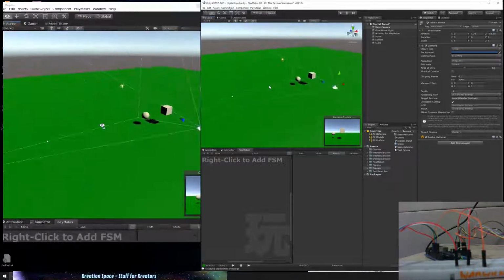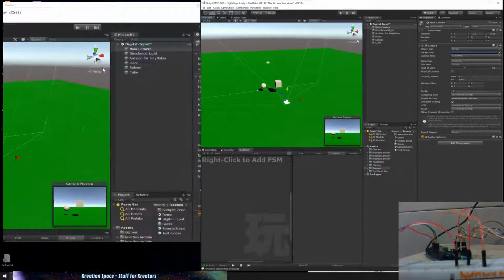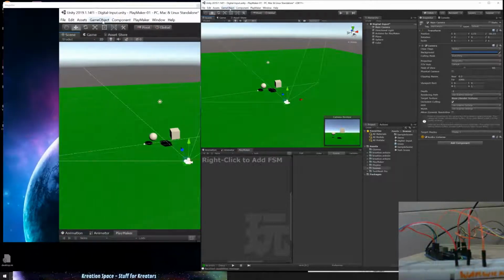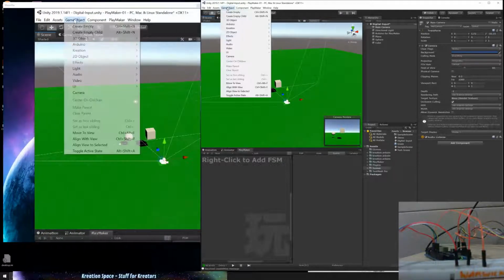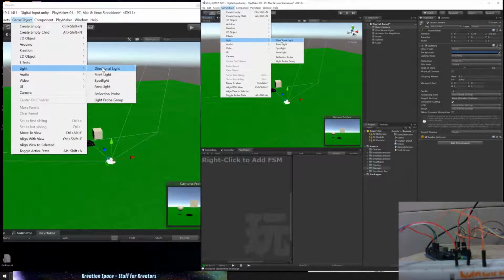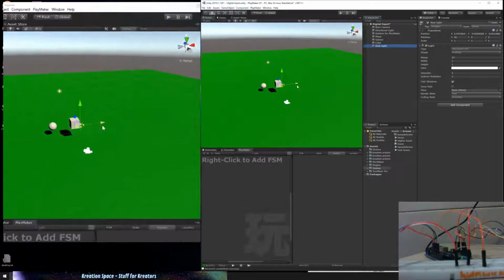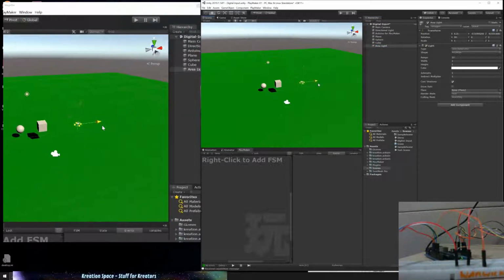Now, one thing that'll help, and it's always good to think about lighting in a 3D scene. So let's set up another light on the side to give kind of just a faint side light or a faint outside light. Let's try an area light. Now, where is it? So let's bring that over to one side.